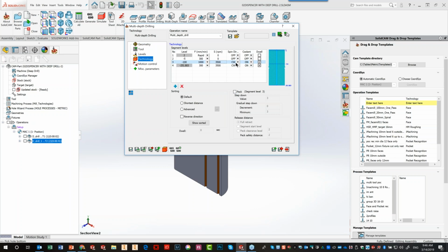Some people may decide that, you know what, while I'm going into a hole that's already drilled, I'm going to go in counterclockwise as not to make it any wider. That's also possible technology which people may want to use. I do not need dwell. Now the next step over here, I'm just going to go down now to the very bottom.